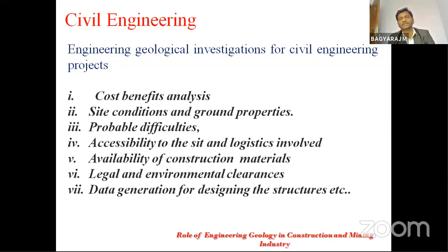If we don't invest in investigation, after the construction we may have some problems which result in carrying more money as compared to what we saved during the investigation. So it has been said that you should pay for investigations whether you have one or not. Now, the ground investigation required varies for particular projects. For dam projects, it will be different.